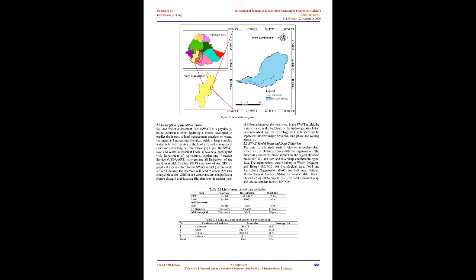It is still one of the problems for the river ecosystem around the world. A study was done on the world's 145 major rivers with consistently long-term sediment records, and the results show that about 50% of the rivers have a statistically significant downward flow trend due to sedimentation. Land degradation due to soil erosion is a major problem facing Ethiopia today. In most of the catchments, soil erosion is caused by intense rainfall, steep topography, construction, and poor vegetation cover coupled with the cultivation of steep lands and inadequate conservation practices. Hence, the more pressure exerted on land, the more it leads the soil to lose its structure and cohesion, which means it can be eroded more easily.